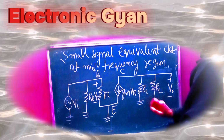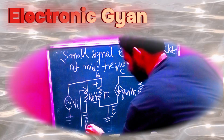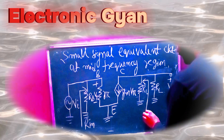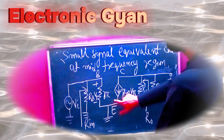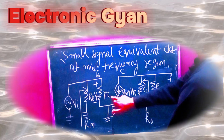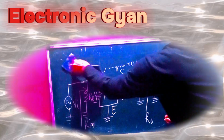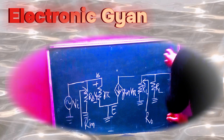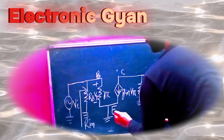So now we are going to find first the input resistance seen from the input side, and the output resistance seen from the output side. If you see, Rin is this, and R0 is RC, and Rin is the parallel combination of RB and R pi. Let's say I will calculate this here. Every calculation I will do here only, because I have to keep this circuit with me. So here is base, and here is collector, here is emitter.